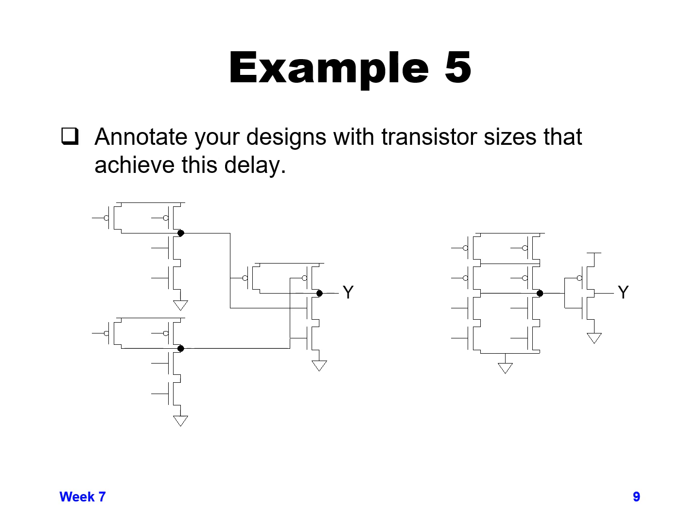So if the input is 16, keep in mind that since we have two NMOS in series with each other, the NMOS are going to be the same size as the PMOS. So if we have 16 and NMOS are the same size as PMOS, the left hand side would have size 8 for both the NMOS and PMOS transistors.